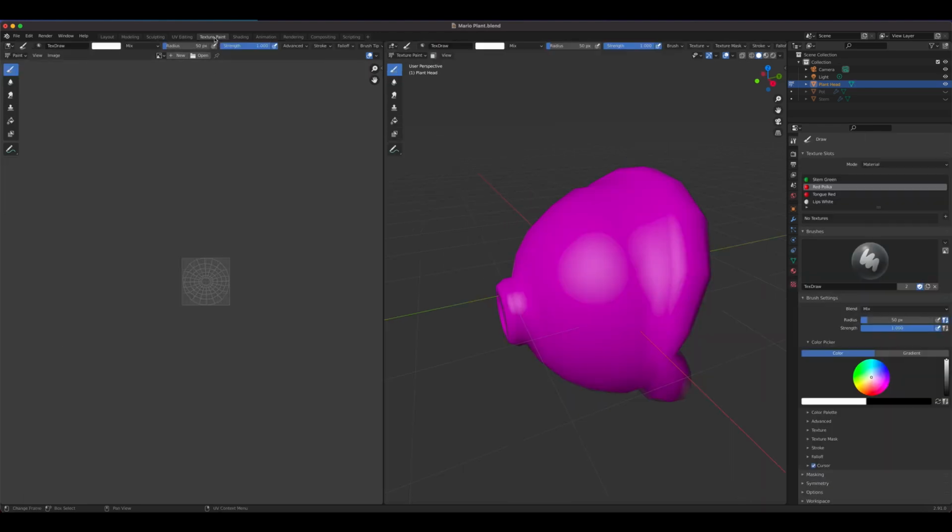Okay, let's go to texture paint and then let's have a crash course here. Make sure that you have the material that you set for that part that you want to paint to be selected. Right now Blender is reporting there's no material on this one. So it says no texture. What do you want to make on this one? We want to make a base color. So I'm going to click plus, base color. Then it's going to ask us for the name. We could actually leave that name. It's pretty good. The red polka base color.